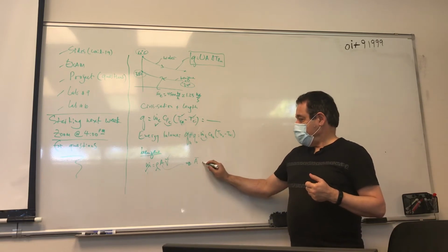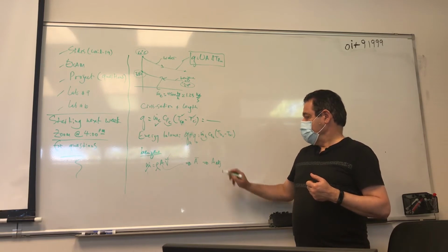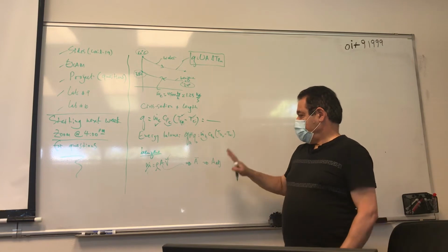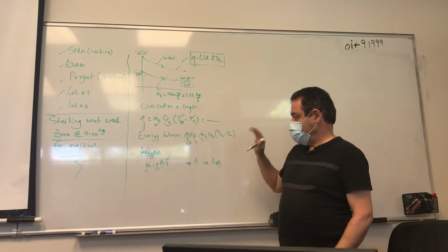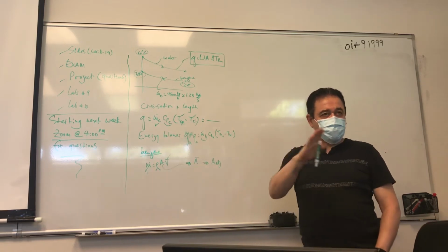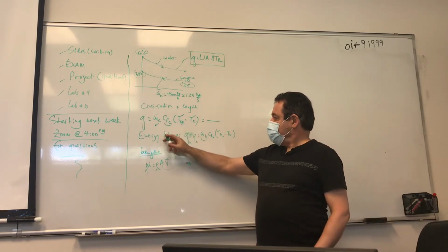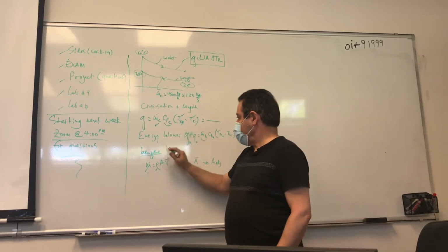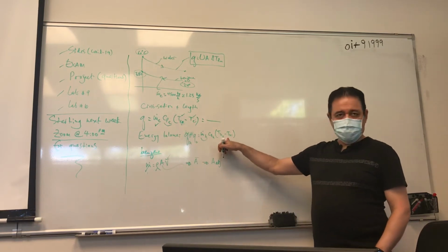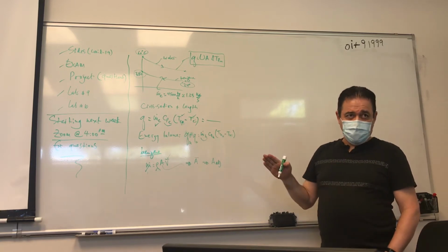So, A and then A adjusted, right? Once you get A adjusted, now you're fine. That means you really have adjusted the velocity. That's why I said don't start with the edges. Once you find this, another way is to come back here and try to find the outlet temperature of the cold water. You may have to iterate on that one.